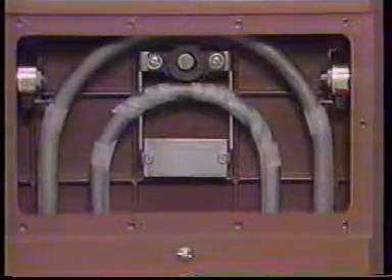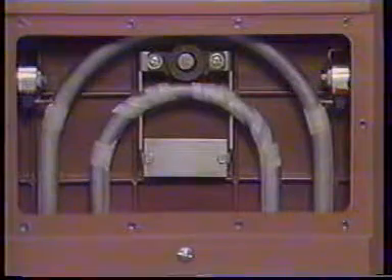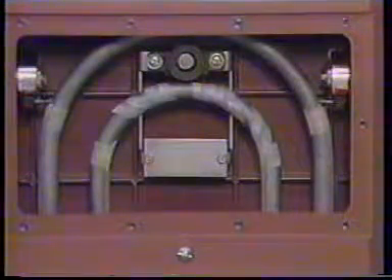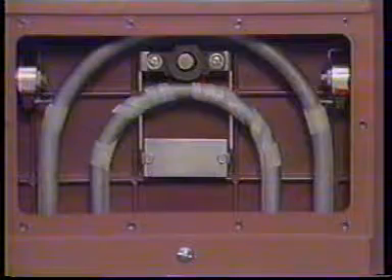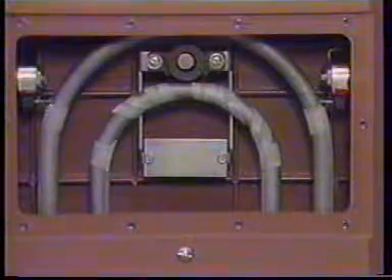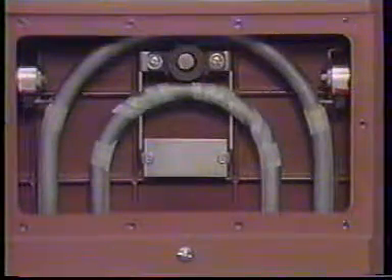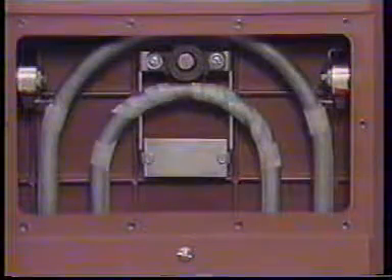The amount of deflection is detected by an optical or magnetic sensing device and is proportional to the mass flow rate. The tube has no moving parts in the process stream and offers no obstruction to the flow path. This type of flow meter may be used for low to medium viscosity liquids and slurries. It may also be used for mass flow measurement of gases if the density is sufficient to generate the force necessary to produce a measurable deflection in the tube.